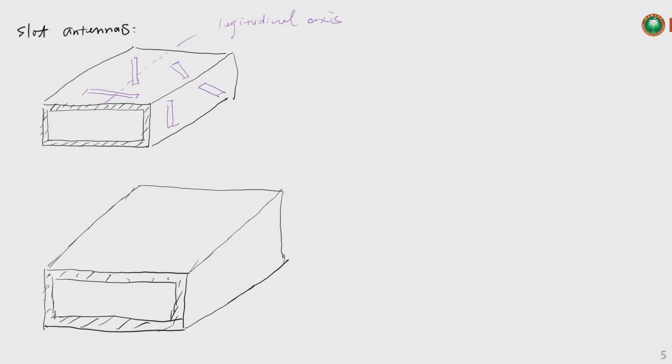So if we have an electric field input in this direction, and the current flow, or the surface current, usually for the rectangular waveguide we just consider the TE10 mode, right? So this is the basic dominant mode, really. And so the current, where is the current going to go? Like this one, right?